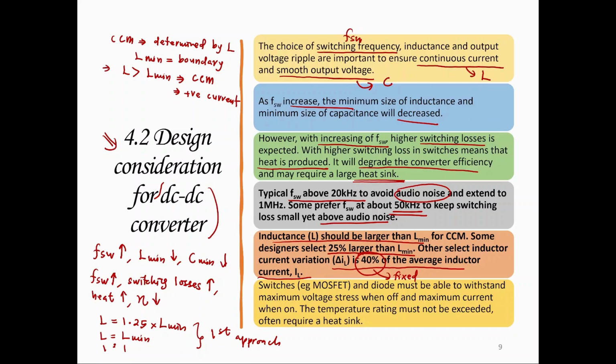Okay, the last point is with regards to switches. So you can use any type of switch as long as it is able to withstand maximum voltage stress when your switch is off and maximum current when your switch is on. Okay, and also you need to take care of the temperature rating so that it will not be exceeded, or else you need to have additional protection in order to avoid the switch from damaging.